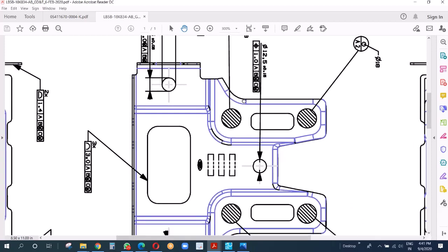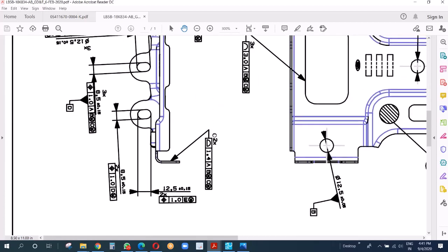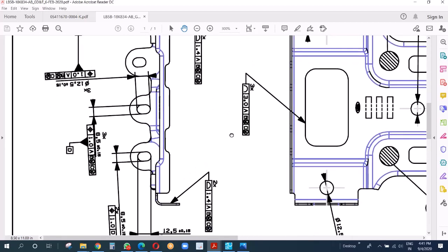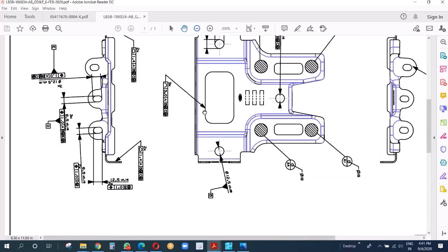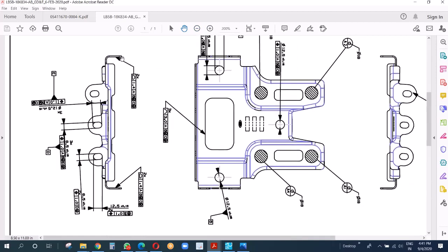And now we go to these two flanges. These two flanges have plus minus 0.7. It's a surface tolerance over here, right? And then these oblong hole sizes are 8.5 into 12.5 with the positional tolerance as mentioned, plus minus 0.5, right? And those two are actually datum E and D, as you can see over here, right?